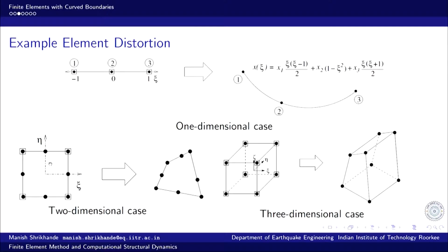In this particular case, the rectangle case, we used only 4 nodes for modeling the geometry, 4 corner nodes, while the primary variable is modeled by using the interpolation between 8 nodes. The primary values are the nodal variables at these 8 nodes in the element, defining the 8 noded serendipity element rectangle.